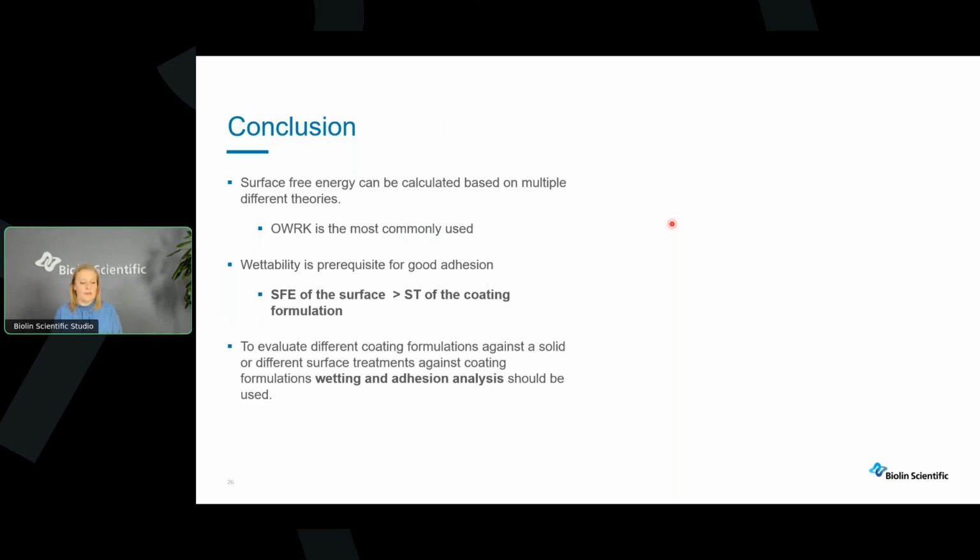And to get good adhesion, this surface free energy is important to understand, because we need to have the surface free energy of the solid higher than the surface tension of the coating formulation.